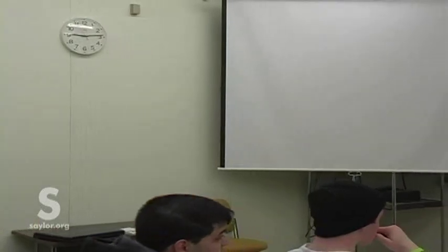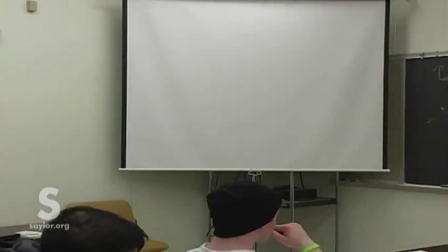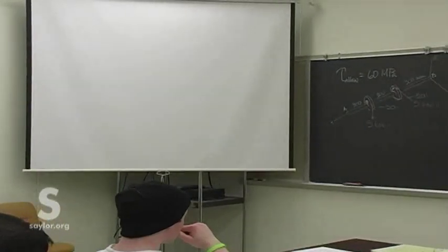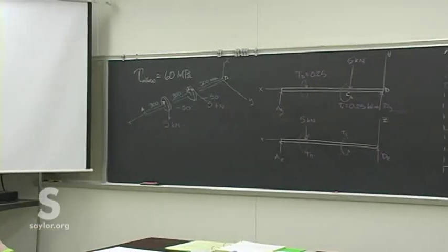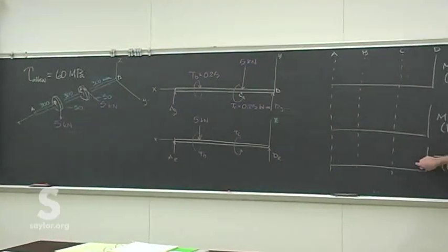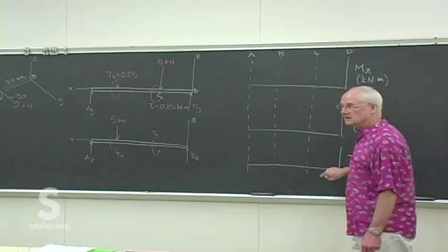For these two moment diagrams, only these forces apply, because that's what's causing the bending. These are torsions which do not appear in the moment diagrams. Those torsions apply down here, the applied torques only apply down there.